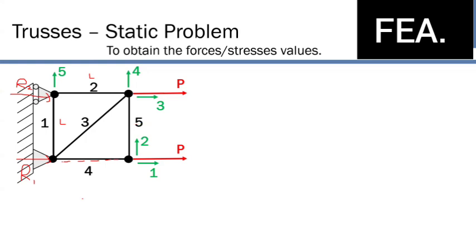So you're not going to be able to use the joint method anymore. You're going to have to use the method of sections and treat them as non-two-force members, as you remember from 101. But for this problem, they are two-force members, so we can break them down into joints. So if we number the joints 1, 2, 3, 4, we can start off with joint 4. Let's start off with x.